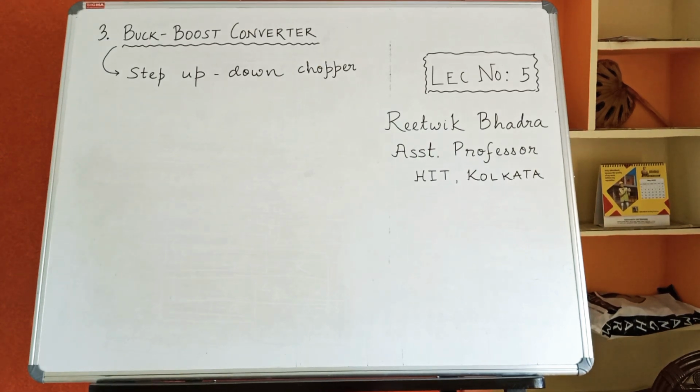My buck boost converter. A buck boost converter is also called a step up down chopper. That means it can either operate in step up mode or in step down mode. The mode of operation depends upon how you choose your duty cycle D.